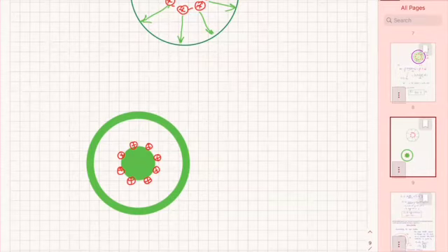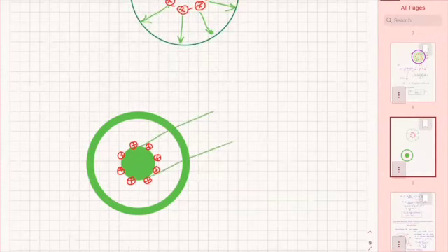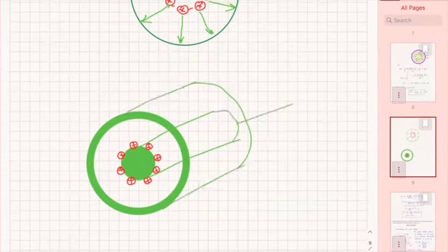So if this coaxial were to be finite, and then somewhere here it would be connected to a voltage source. That's how we have lines. That's what we plug into the power. We have a source. So from the positive end of the source, all of the charges will go on the inner conductor, but where? On the surface of the inner conductor.